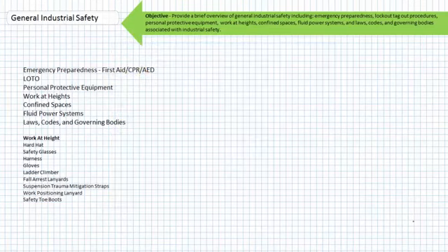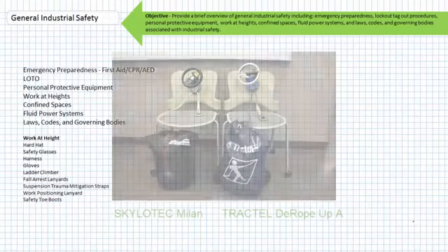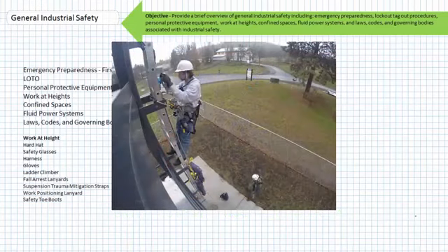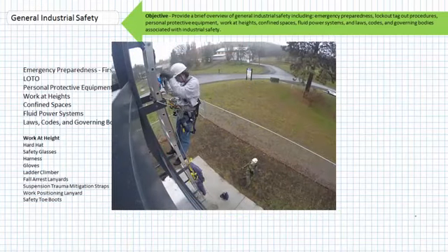In addition to this individual personal protective equipment for work-at-height scenarios, there exist devices for retrieval, rescue, and evacuation. These allow for the retrieval and rescue of a coworker in the event of a fall. These devices are manually activated assemblies with a gear ratio that allows a single person to pull a casualty from the fall arrest system and safely lower them to the ground. Here's a clip of such a device being used for this application.